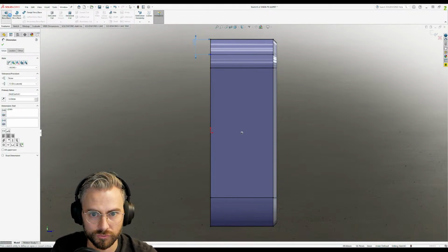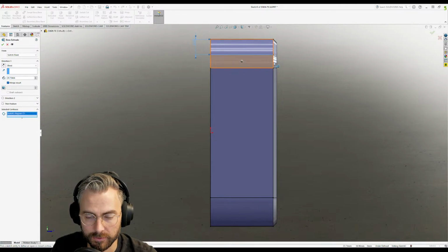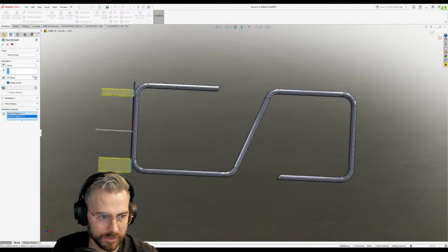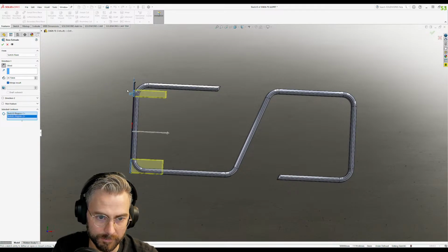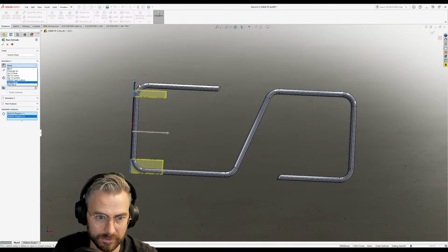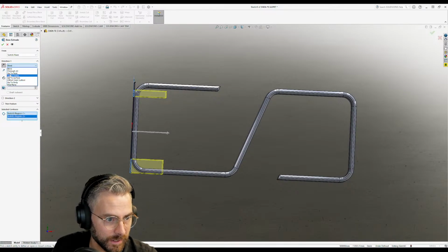And features. Now we're going to extrude this part and this part. So we don't want to extrude it that way. We want to go that way, but we don't want to go blind. We actually want to do it up to body. So we can't go up to a surface because this is actually going to be connecting to 2 separate surfaces. We could do up to a point, but not really.